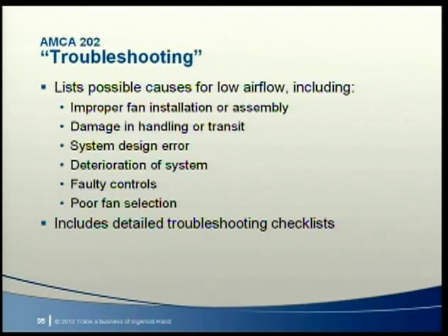AMCA 202 includes checklists and recommendations to help you troubleshoot and correct problems found in fan installations. It adds to the list of possible causes. For instance, a fan may have been damaged prior to installation, or it may not be properly wired or controlled.